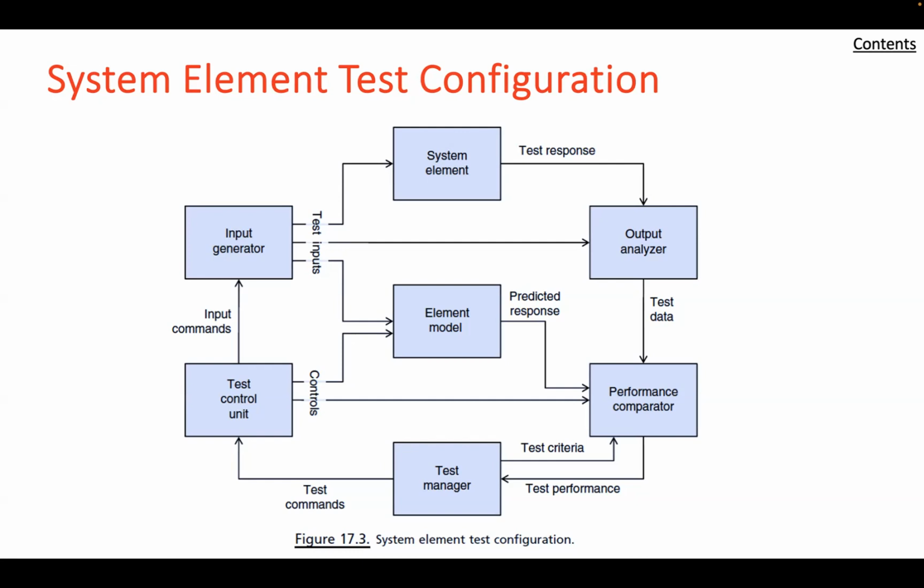To ensure that interfacing mechanical, electrical, or other elements fit together and interact properly, the specifications for each separate element must include the permitted tolerances and the interacting quantities. For example, if the interface components are held together by bolts, the location of the bolts in each component must be specified within a plus-minus tolerance of their nominal dimensions.